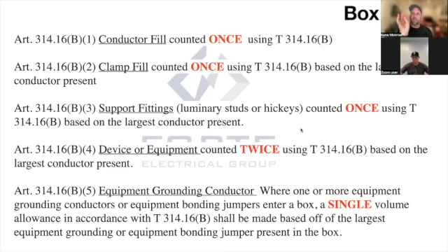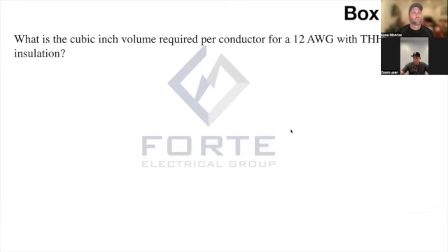Your little lock nut that you screw in the box, holding your EMT connector or anything, does not count on your deductions up here. So it's just like the clamps or like hickeys and stuff like that. Yep, exactly. And they're going to use luminaire studs, and they're going to use the word hickey if you see it, because it's just going to throw people off, because people don't know what that stuff is. We don't use that terminology. So just be ready for that. Okay, so that's how we do box fill.